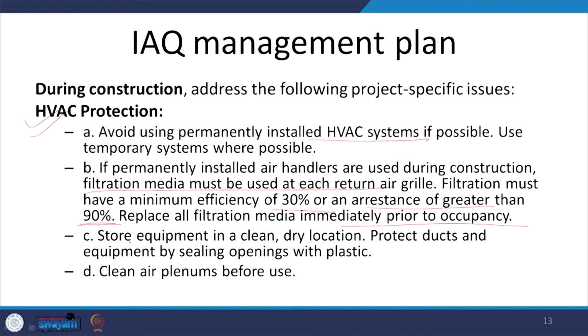Next, the equipment shall be stored in a clean dry location which is free from dust and any other contaminant settling in the equipment, and the ducts and equipment shall be protected by sealing them with plastic. They should be properly covered. And the ducts, whatever has been installed, the plenums, they must be cleaned before use. So, all of that has to be cleaned.